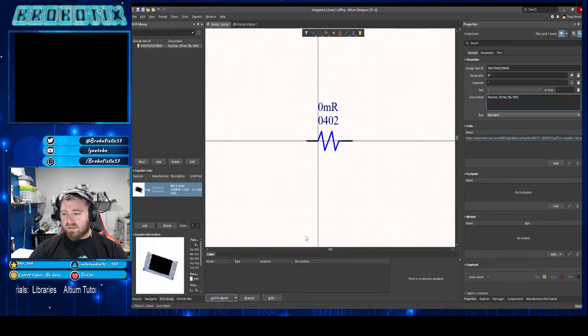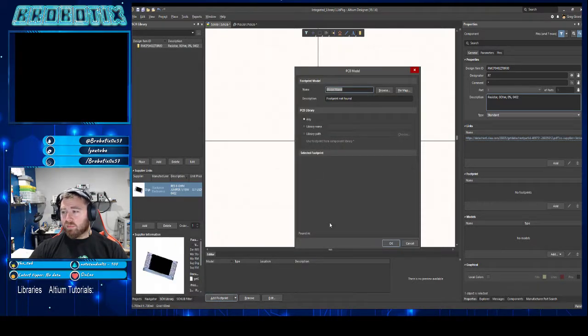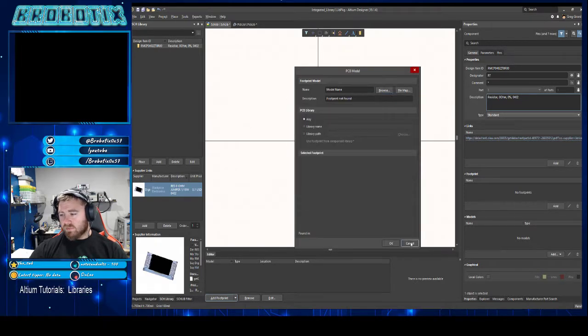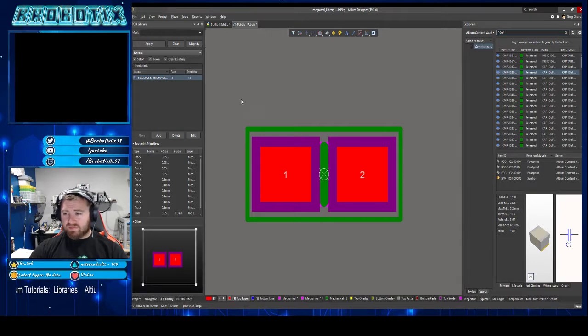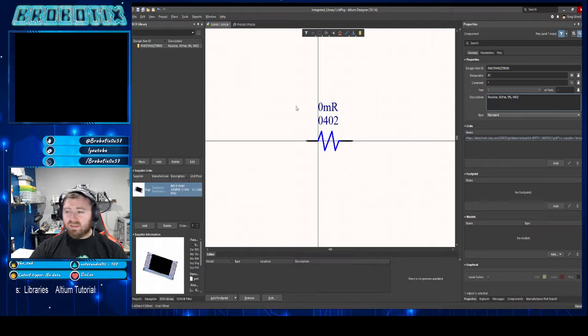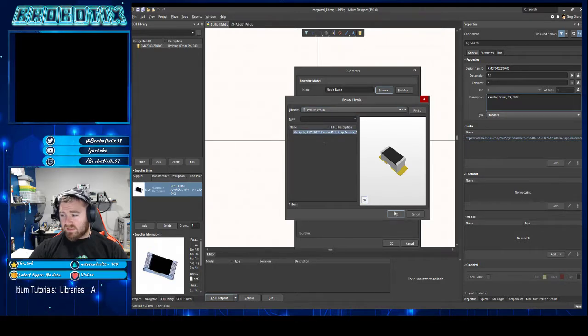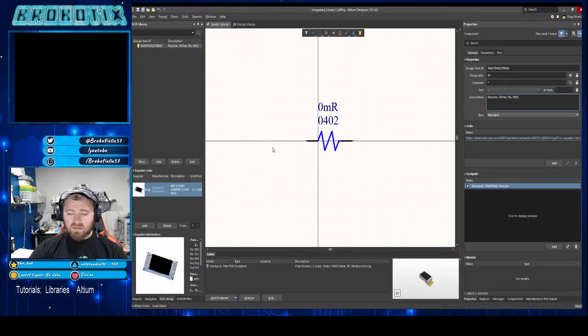I come back here, and the last thing I have to do is link footprint. So you click the add footprint button down here. I'll save this for now. I mean, I don't need it for anything. Save a default spot. Save this. So now I go here, and now it'll pop up. I click this, hit OK, save it, and now you have a working chip. That easy. Maybe 5-10 minutes. Just hammer through it. Pretty easy.